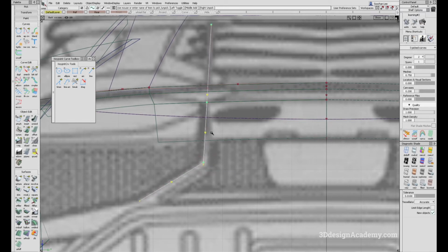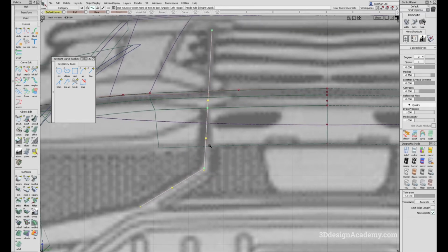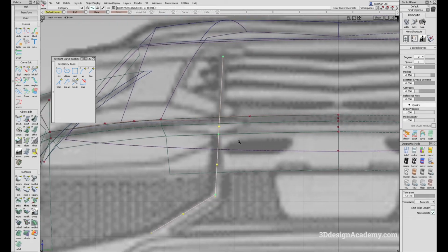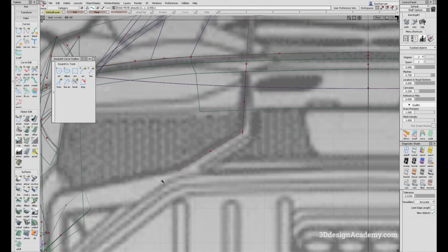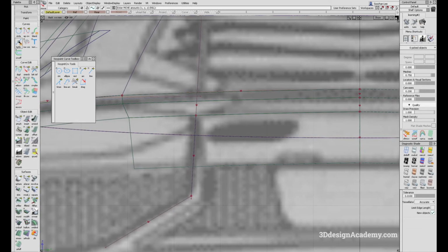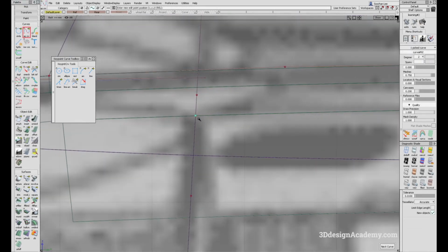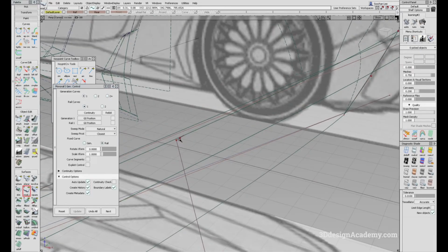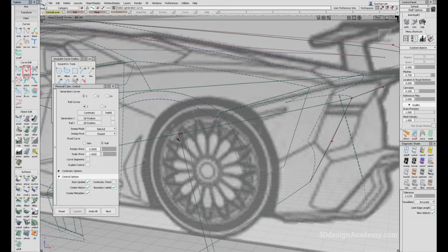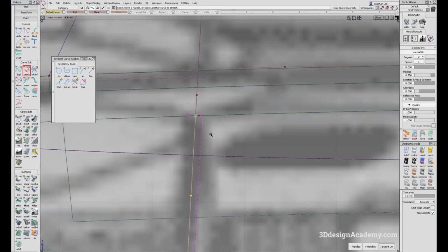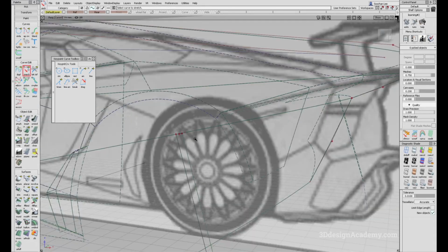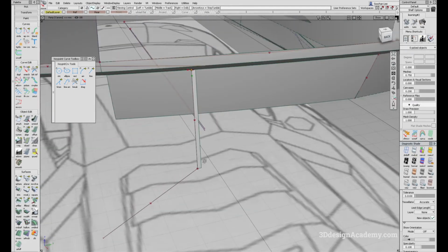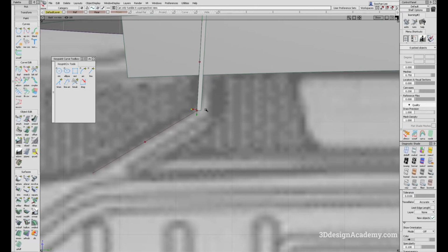Right now, because of the thickness, you have to be either on the left or the right side of this wing-like feature over here. So I'm just going to pick the left side like this, so that we can align this to the top. And I'm going to create a flat like this over here, and do a monorail based on that. Because of the movement that we made, I think we probably want to go forward a little bit. For now, I'm just going to snap it over here. Eventually it'll need to go in and intersect, so I need to be aware of that, but for now let's just leave it at that.